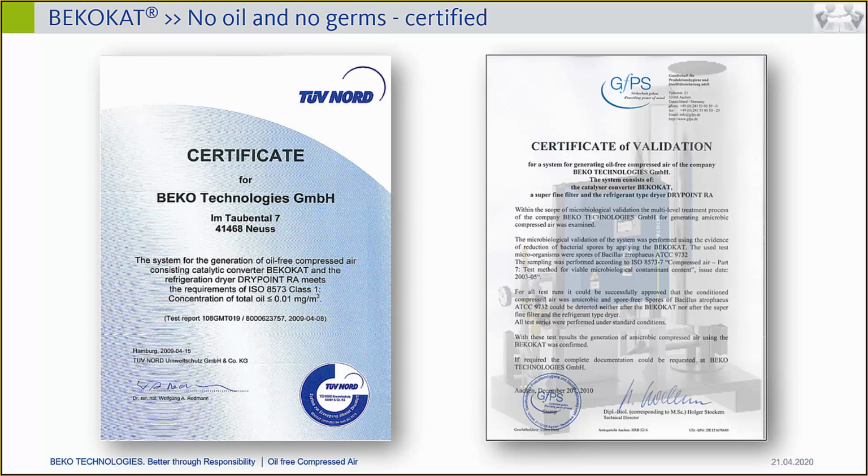What needs to be done in maintenance is that I need to check some safety components: the inlet and outlet valves, and the activation valves of these valves, and I need to change the safety valve. But that is quite a cheap component, and that was not integrated. So in fact, there is maintenance required for the BEKO, but for many years on a quite low level, and only after 5 years the exchange of the catalyst is required, which is the biggest cost-consuming maintenance in this period.